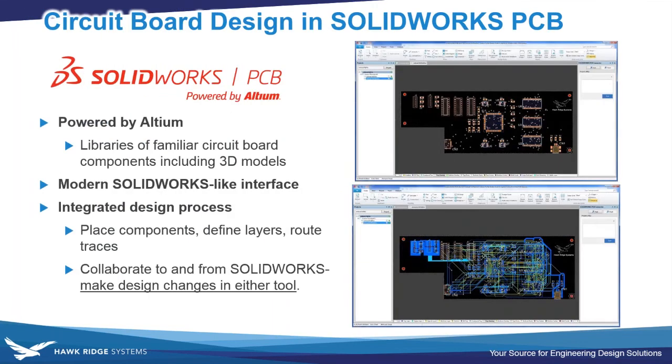Now, of course, if you are designing an electromechanical product, you're going to have a circuit board in it. And in many cases, you might be using a newer product that came onto the market a couple of years ago called SOLIDWORKS PCB, which is, of course, a circuit board layout tool based on Altium Designer. And if you choose to use this tool or something like it, you'll either be collaborating your board layout directly into the SOLIDWORKS 3D model, or you might be importing some other kind of board file like an IDF through CircuitWorks.